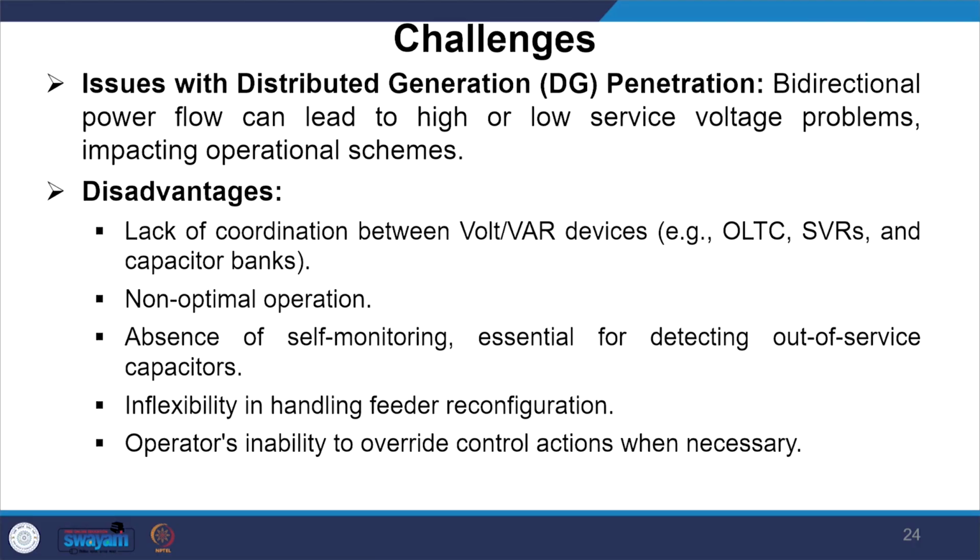Now, what are the issues and challenges? Lack of coordination between volt-var devices, that is OLTCs, SVRs, and capacitor banks, which cannot make optimal operation possible. Absence of self-monitoring, essential for detecting out-of-service capacitors. Inflexibility in handling feeder reconfigurations, and operators' inability to override control actions when necessary.